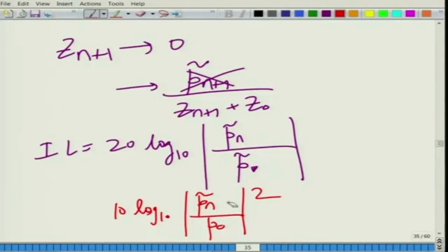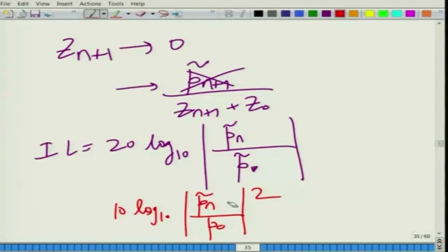However, if we were to predict it analytically or through some numerical finite element scheme, once we know the characteristics of the muffler, if we can relate the upstream and downstream variables through numerical modeling and evaluate the four pole parameters, we will talk about that sometime later. And once we want to evaluate the insertion loss through some numerical scheme, it is a much more complex task, because we need to know the source characteristics P n plus 1 and Z n plus 1, or Ps and Zs.